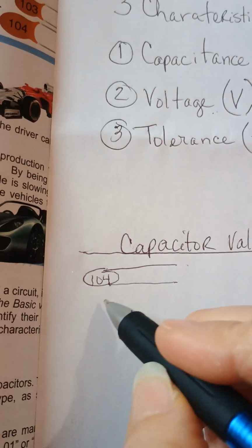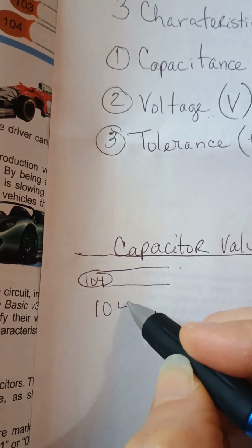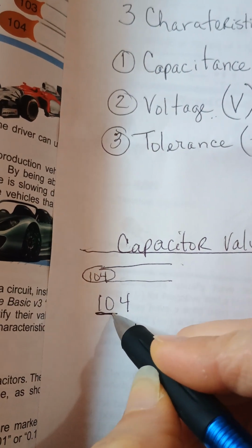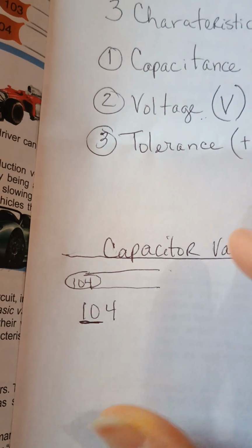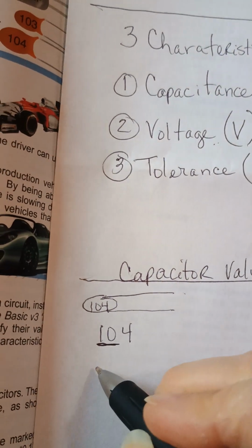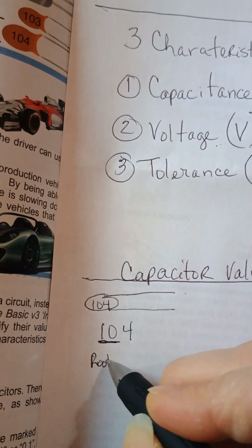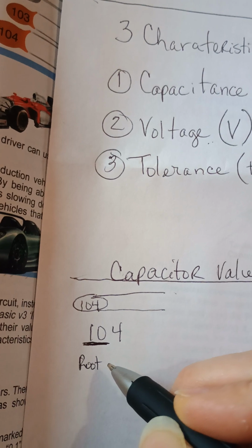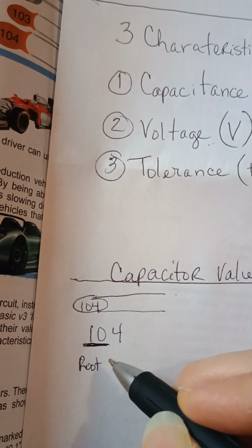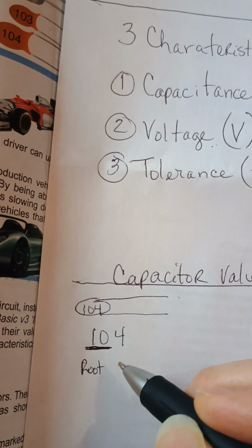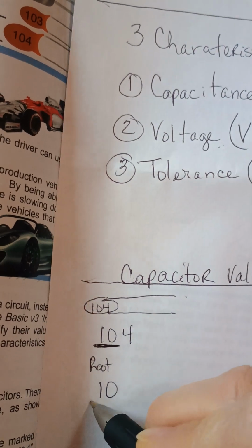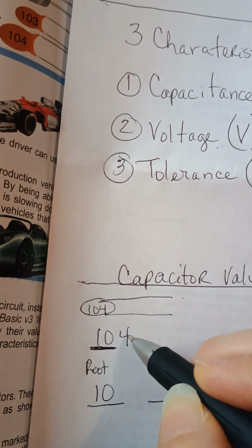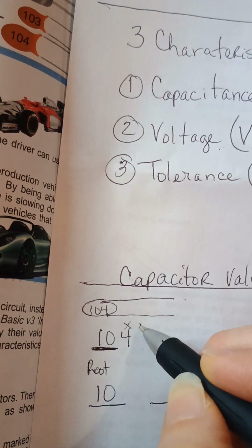resistors, we simply can take this number 104 and rewrite it. I'm going to underline the first two because that's my base number, or I could also call it my root. And I like to be consistent, so I'm going to write root underneath it. If you like the word base, you can go with base, but we used root for our resistor, so I'm just going to stay with root. So this is my root number. It means it's just going to come right down into my answer. And that's my first answer. Then this 4, my leftover number, is my multiplier number.